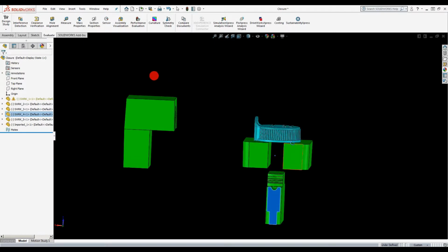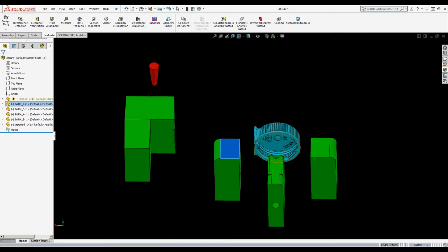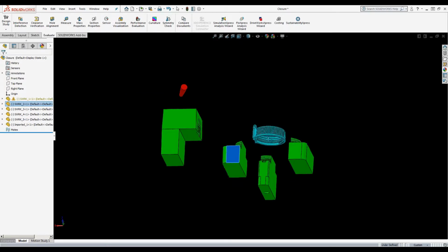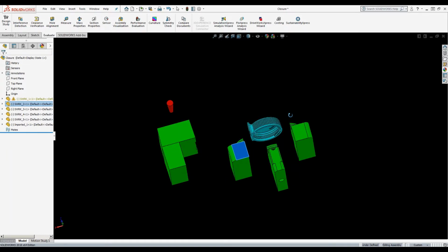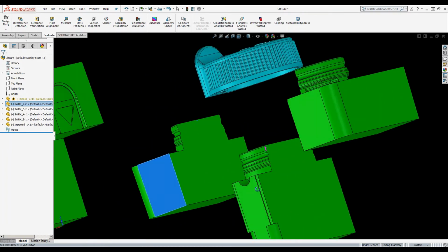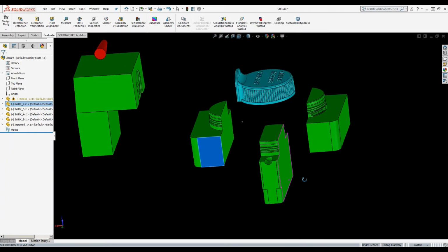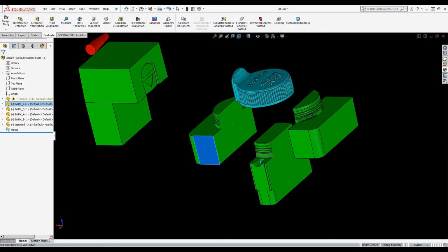Operator would come out, pull this one back, move it out, pull in, remove it out, thus creating those internal undercuts. John's pretty much explained exactly how that's done. The motions he showed is exactly how the operator at the press would demold this part, that center core piece staying with the tool as it pushes forward with the inserts, and just pull them away from the threads and undercuts, and the part is clear.